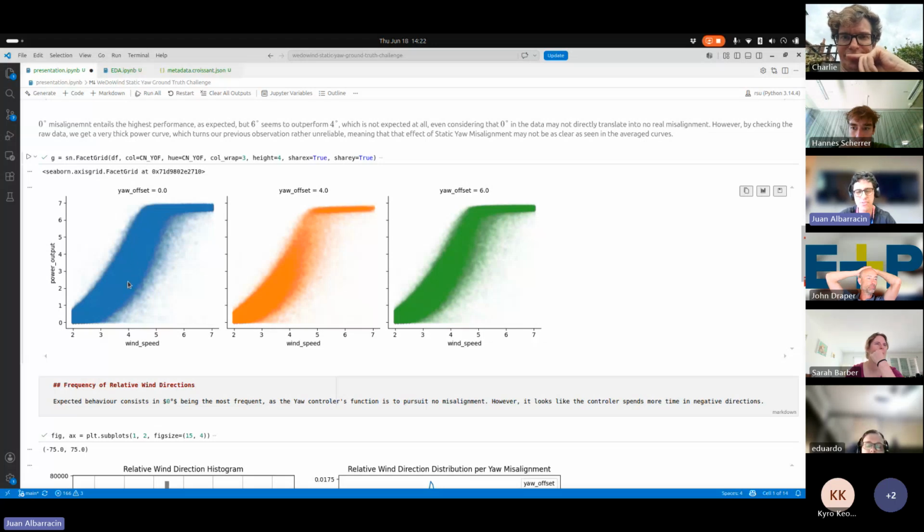And this may suggest that there is another performance problem, with all the points below in the range. The metadata says that the rated wind speed of this model is 7 meters per second, but empirically we find that it gets the rated power at a bit more than 4.